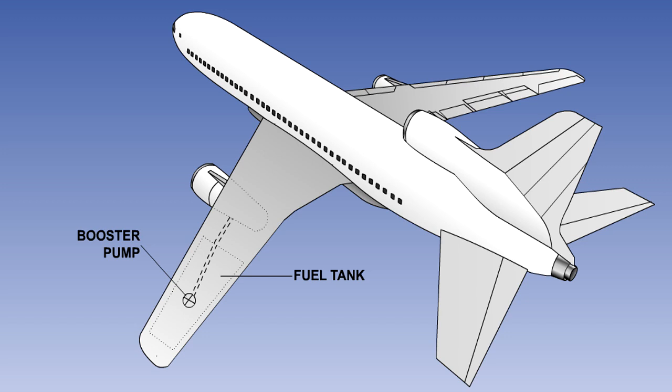The vapor locks that this effect causes can cut off the fuel supply to the engine, with the result that the engine will stop. Fuel booster pumps fitted inside the tanks can help to overcome this problem by pressurizing the fuel in the pipelines from the tank to the engine, pushing fuel towards the engine rather than engine-driven pumps sucking fuel from the tanks and further reducing the pressure.